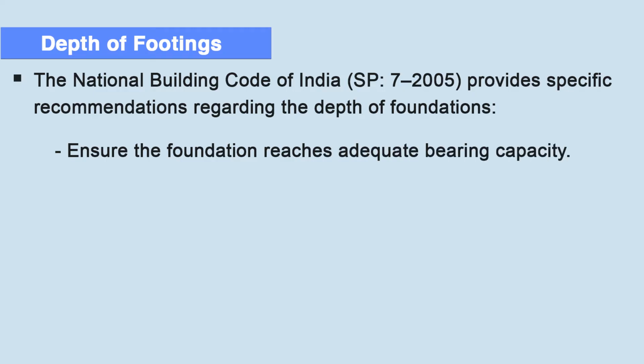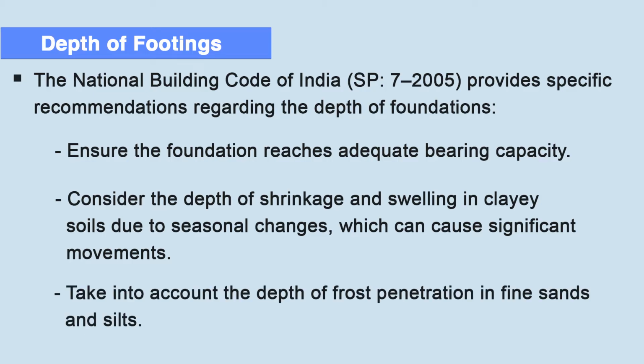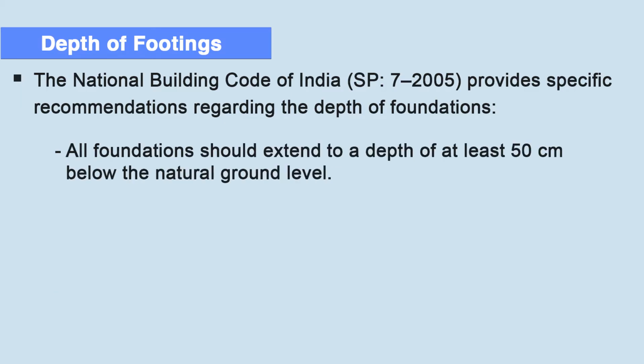First, ensure that the foundation reaches adequate bearing capacity. Second, consider the depth of shrinkage and swelling in clay soils due to seasonal changes, which can cause significant movements. Take into account the depth of frost penetration in fine sand and silts. All foundations should extend to a depth of at least 50 cm below the natural ground level.